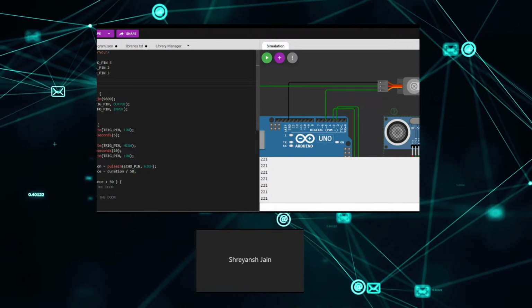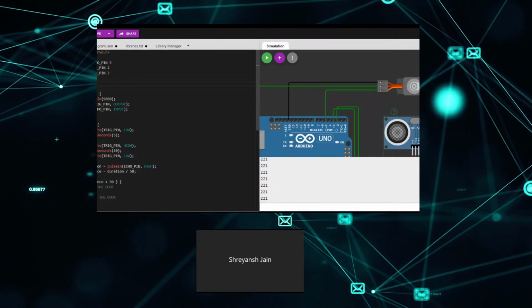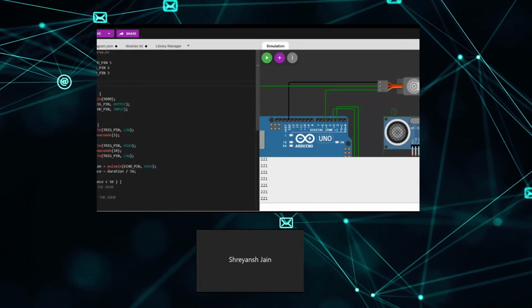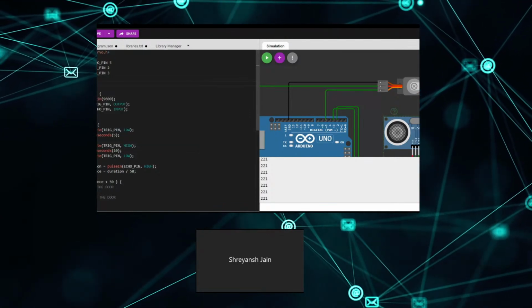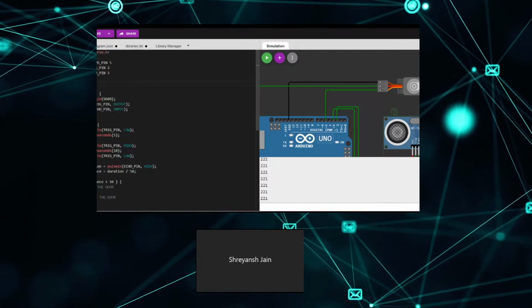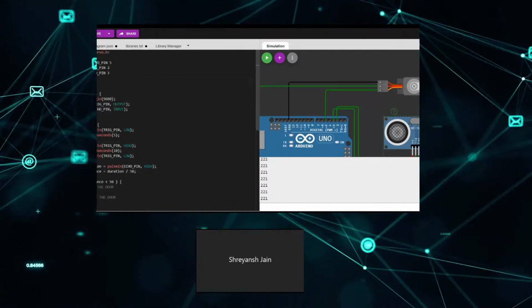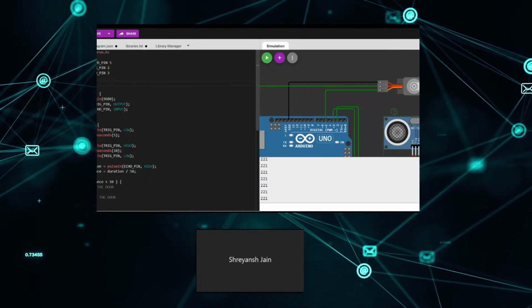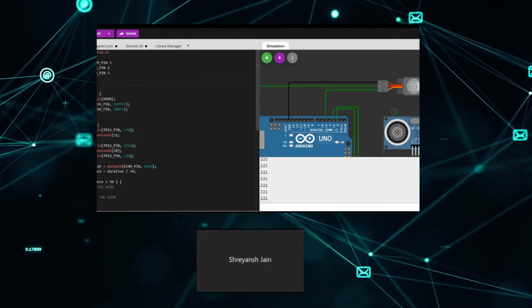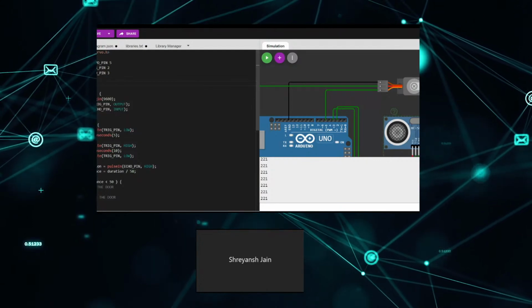We are not going into details of that right now. I'm just going to give a brief overview of it. So what it does is it gives us a custom type. Like we have an int, like we can create variables like int, or it can be char or something else, right? We can create variables of different types. So the servo.h library gives us a custom type, it is servo. We create a variable of servo.